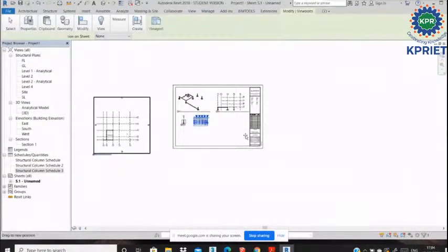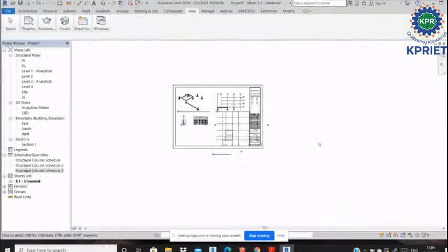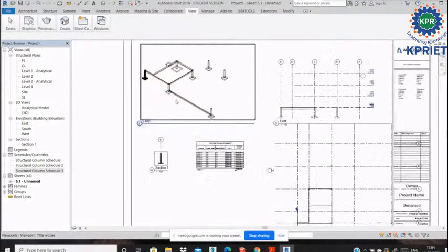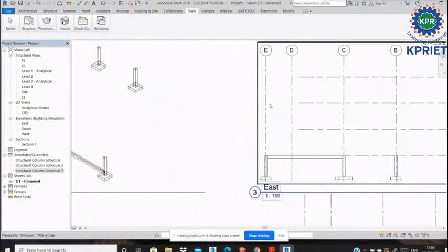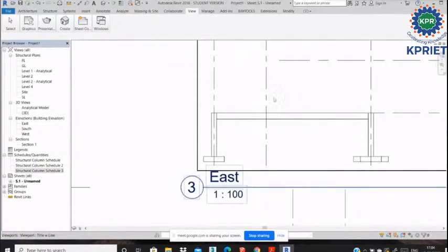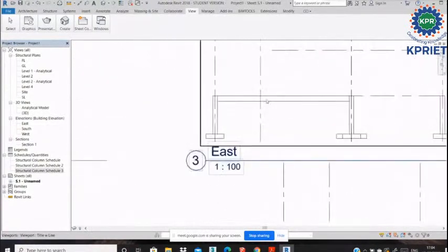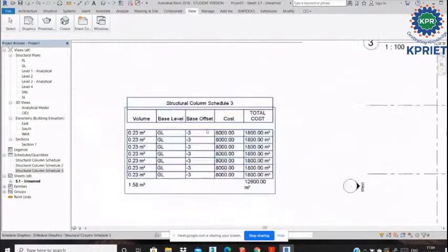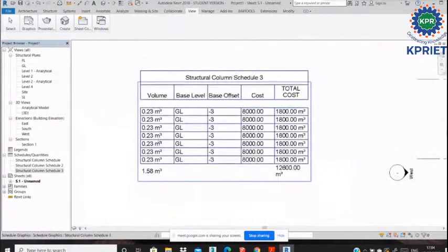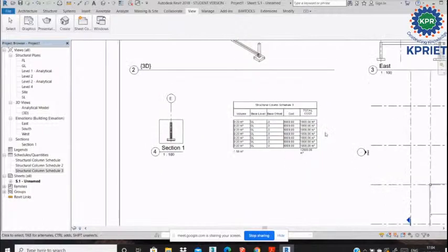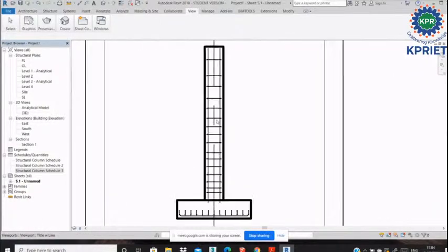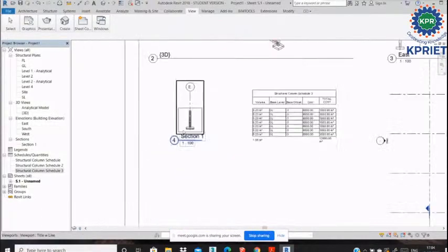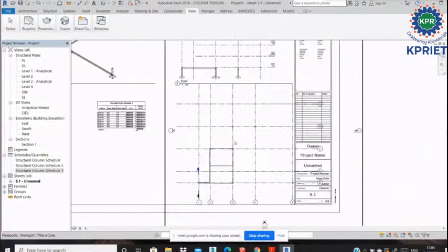Now we see how to create your sheets and so on. Simply create your 3D beam column diagram, then create the grid lines also. You create the top view and other views, and schedules will also be created: how much concrete volume is needed, how much amount you will need, the total cost. Then how to create the rebars and cross sections of your beams.